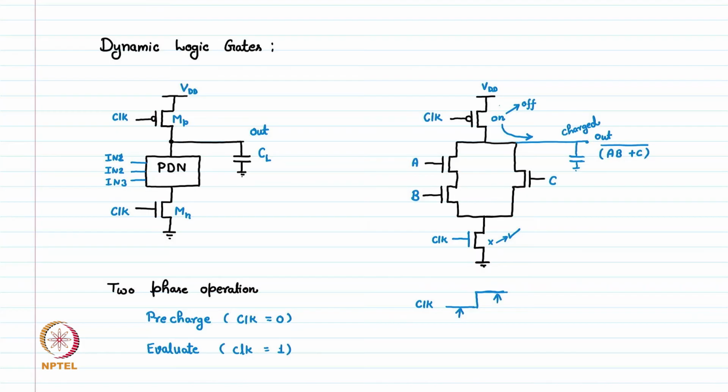It reduces the number of transistors needed to implement a function. We are not using any PMOS devices except for one, and only the pull down network needs a similar amount of devices as static logic, and still we have full rail to rail swing. The output is discharged completely to ground and charged completely to VDD. So let us write down these few properties of these dynamic gates.